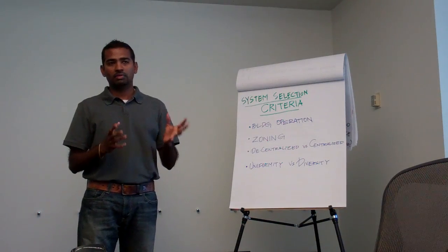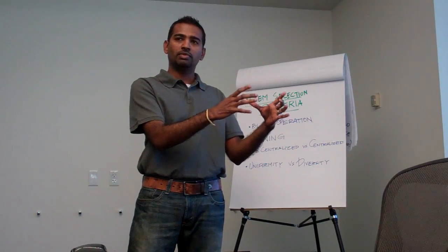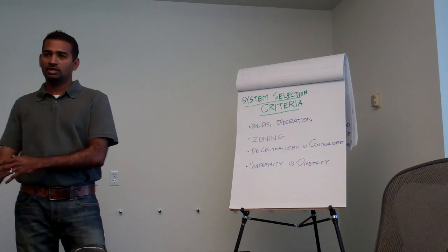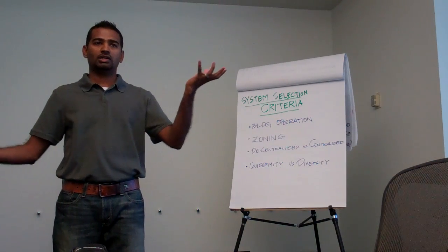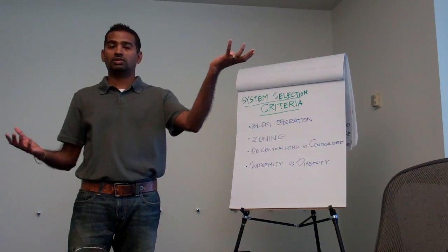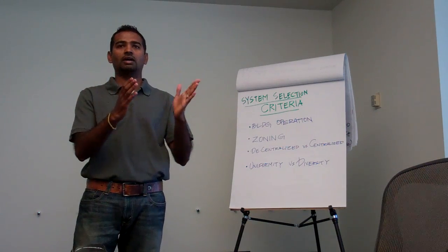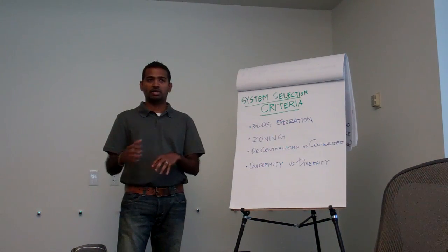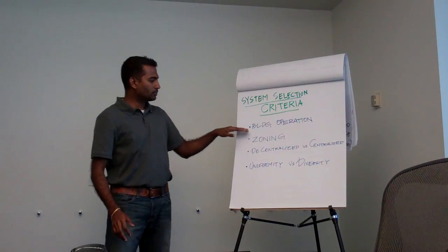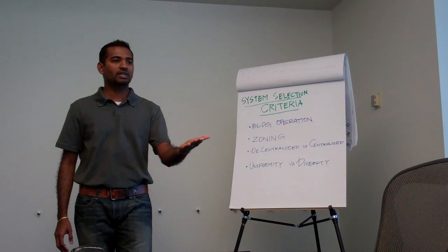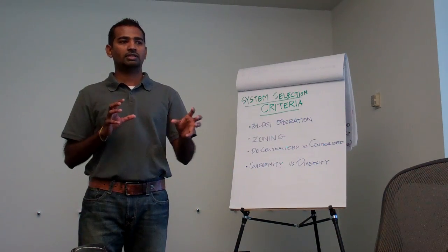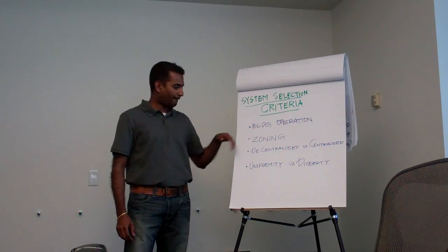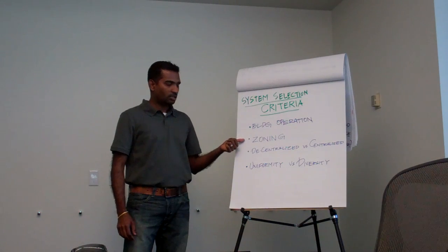Might not, because just to keep the gymnasium running, I may have to turn my chillers on during the weekends. The rest of the school doesn't need it. So there are so many ways to look at this design based on just operation. It is important to understand which portions of your building need different operation than the normal operations. And this gets more complicated when you have a convention center or a hotel, because those different spaces have different operation times. So it is very important to first ask this question. That helps you zone it appropriately.